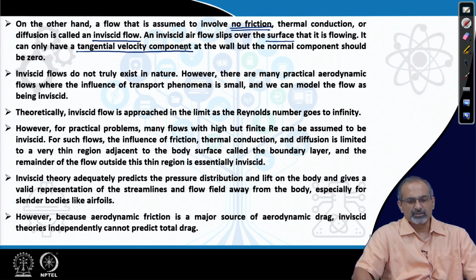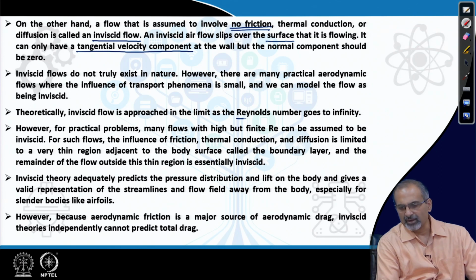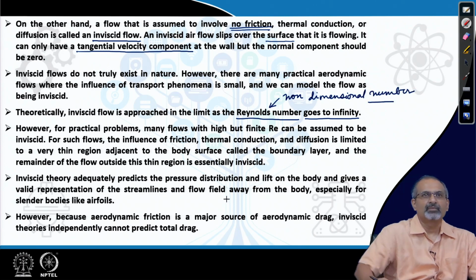Now, inviscid flows do not truly exist in nature, they are basically hypothetical. However, there are many practical aerodynamic flows where viscous influence is very small, and we can model the flow as though it is close to inviscid. Theoretically, inviscid flow is approached in the limit as Reynolds number goes to infinity. We will discuss more about Reynolds number. It is one of the very important non-dimensional numbers, which is of enormous importance in aerodynamics.